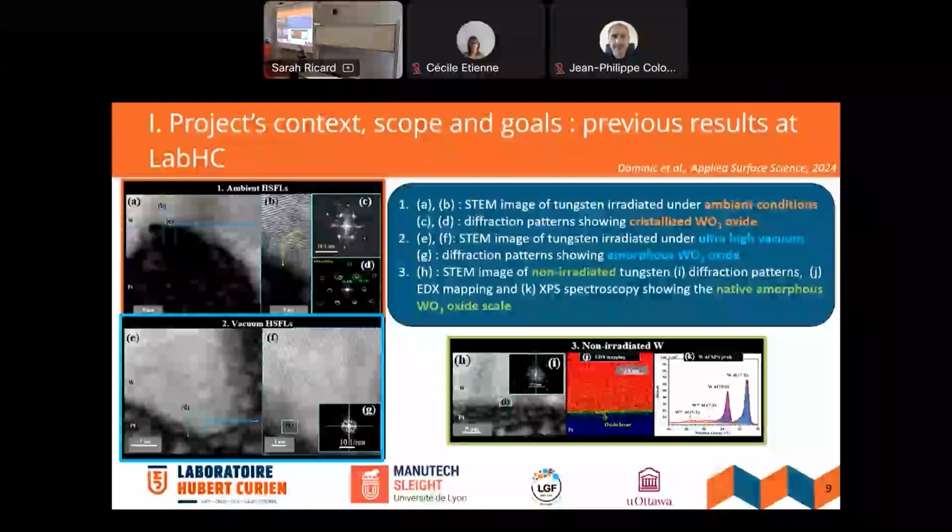So in the case of this article for tungsten, where there's been a two temperature model coupled with molecular dynamics simulations, the sample reached a temperature of, if I'm not mistaken, 6,000 kelvins and stayed above 1,000 kelvins for about 7 nanoseconds.